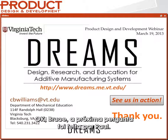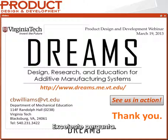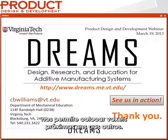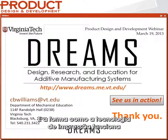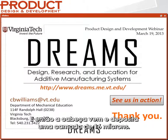Yep. Okay. Bruce, the next question comes from Paul. Are the separate polymer materials bonded? Yeah, that's actually a great question. They are. Again, as I referenced before, the technology allows us to place voxels one next to each other. And the way the actual printing technology works is it actually layers down, as Chris referenced, a 16 micron layer. So the heads come over and it layers down a layer of 16 microns.